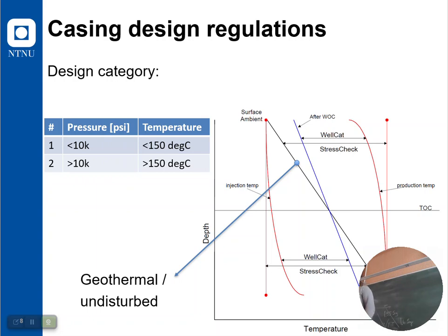Yeah, what I would like to know is, in your case of production, is it the production tubing in the problem, or is it the casing that is submitted to that temperature? All of them. Absolutely all of them. What we need to do, and what makes the temperature modeling so advanced, like I told you, it's like a sandwich. You have first the fluid from the reservoir giving off its energy, the heat, to the tubing. Then whatever is in the annulus, very often in the A annulus, there's a brine.